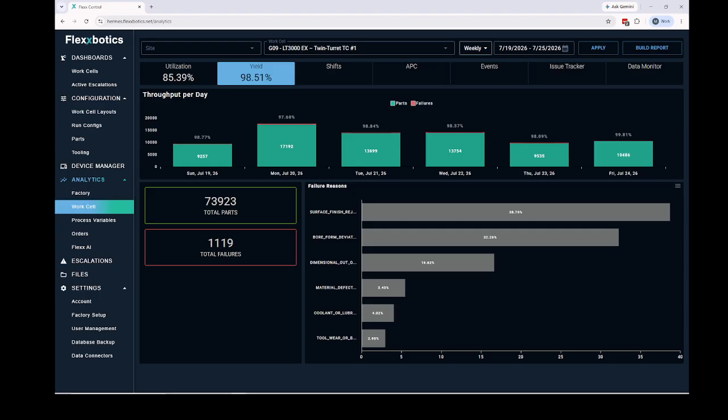While this demonstration is covering a machining environment, the platform can contextualize downtime from a number of different processes and parameters. An injection molding example might be a short shot failure, where a lack of injection feedback pressure is recorded and noted. A press or stamping example could be when a die is wearing thin, measured by peak tonnage per stroke climbing steadily across an individual shift. This kind of data insight helps manufacturers identify production issues quickly and with accuracy, while defining exactly how those problems could affect profitability and output.